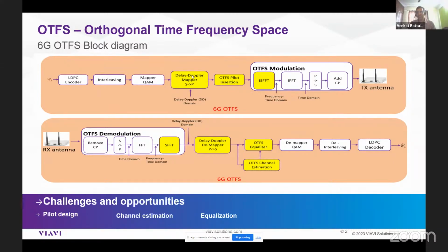The characteristics of the channel are the delay, which comes from multipath, and the Doppler, which comes from the moving aspects of the connected device, be it the UE or the train or something else. It's a classic scenario where you can represent your channel in the delay-Doppler domain, which is actually the physical world. So that's the quick basic introduction.